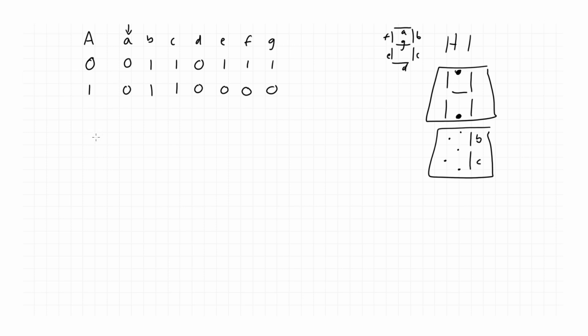So let's look at the Boolean expression for segment A. Well, this is pretty easy because A is always off. So A equals 0, and that equates to being connected to ground or 0 volts. B, the output segment B is always on.